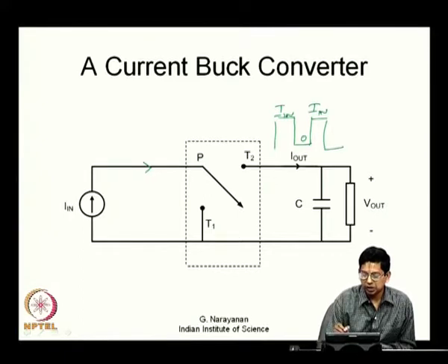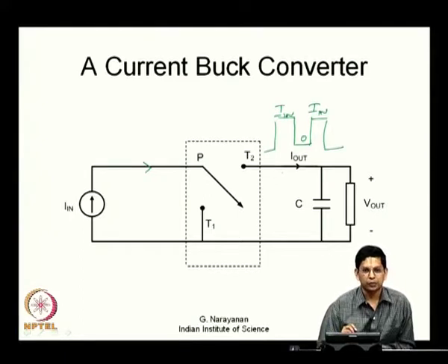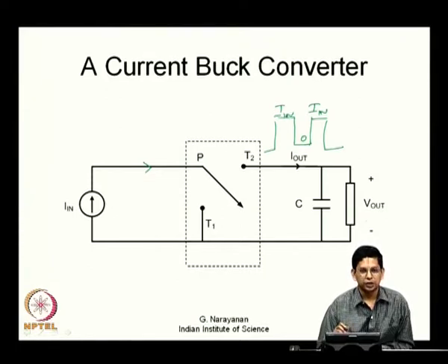You have such a pulsed current flowing through this now. This pulsed current flowing through a resistive load will produce a pulsed voltage waveform. You can smoothen the voltage waveform considerably by putting in a capacitance across this, as we discussed the other day. Anyway, what we are worried about is the output voltage V out now.